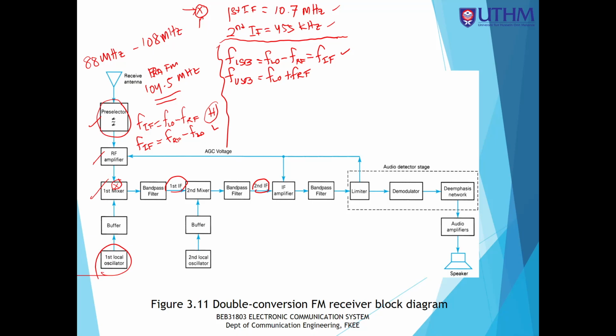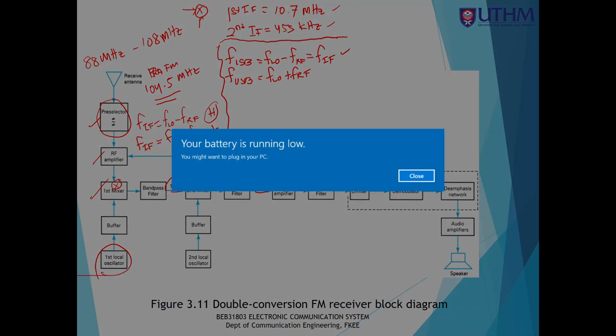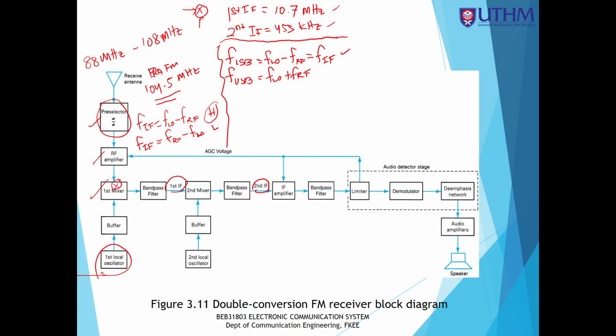We already know the value of the IF. We know the IF frequency that we want by standard: it is 10.7 megahertz and 455 kilohertz.